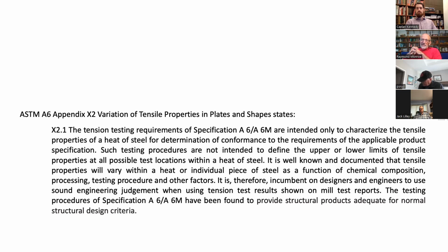It's not just a casting issue. It's also a forging and a plate issue. Take the ASTM plate, bar, and sheet specification, the oldest specification that's still active in ASTM. One of those odd things that people don't know is that the ASTM standards are sequentially numbered, so the lower the number, the earlier the standard. ASTM A6: A is the steel committee because it was the first committee, and 6 means this is the 6th standard that ASTM ever wrote. So this standard is like 100 years old.